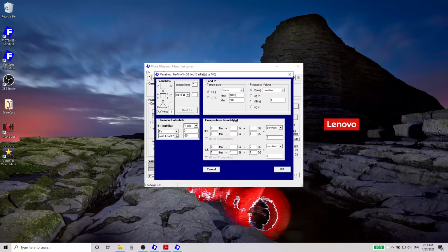To select the species, we have to select oxygen. And then in y-axis, we have to select for which range of partial pressure you want to check. So we'll check from 10 to the minus 40 atm to 10 to the minus 20 atm as maximum.